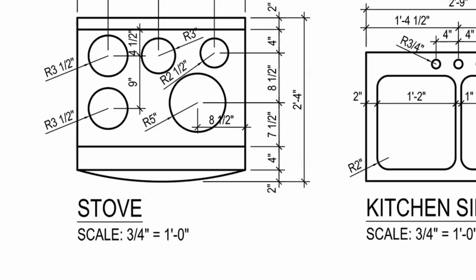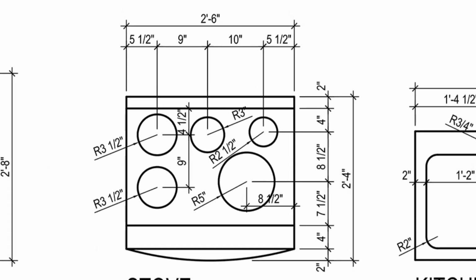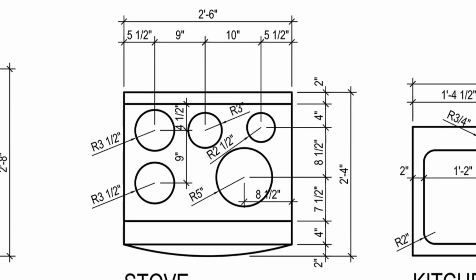The next thing I'd like to do is to find the center points of the different circles. So I'm looking at the dimensions, and I'm going to start with the 2 burners that are on the left-hand side. And I can see that I have to offset a line, that vertical line, 5.5 inches over. And then I have to offset the horizontal line 4.5 inches and then bring it down 9 inches. And that's just to establish the center point. And once I'm done establishing the center point, I draw my circles and then I erase the lines that I don't need. Back to the drawing I'll go.